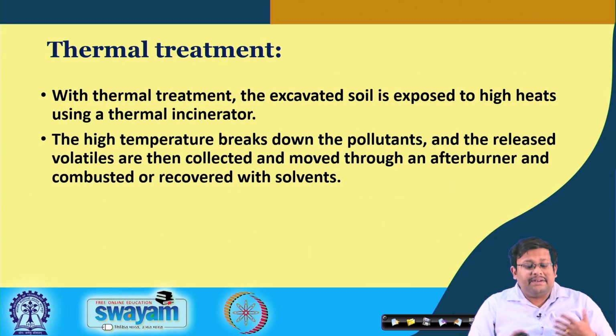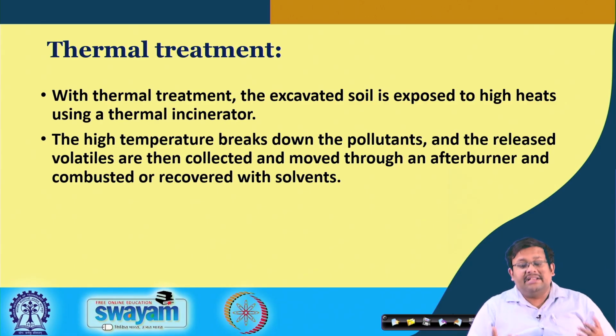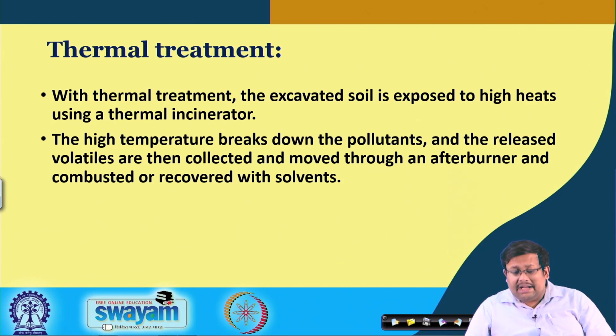Now, the next treatment is known as thermal treatment. Sometimes we call it incineration. Remember that with thermal treatment, the excavated soil is exposed to high heat using a thermal incinerator, and the high temperature breaks down all the pollutants and releases different types of volatiles, which are then collected and moved through an afterburner and combusted or recovered with different types of solvents. So, this is how the thermal treatment basically works.